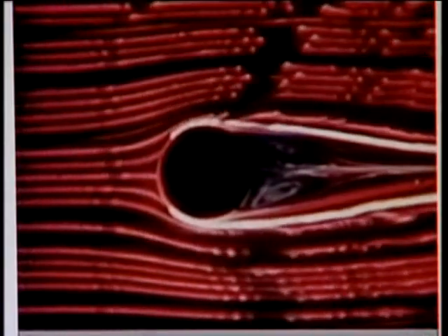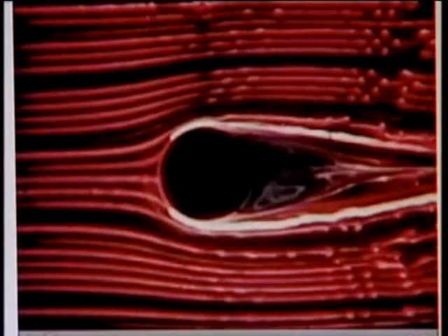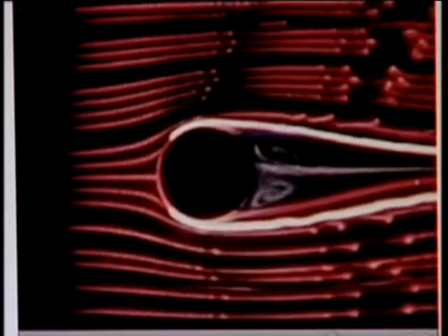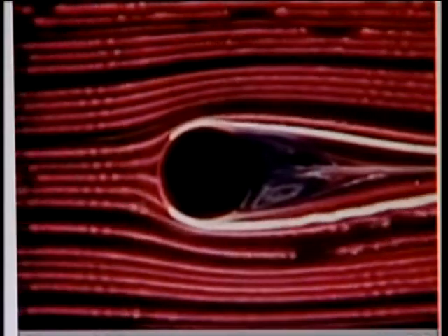In this figure, we can easily appreciate, as this fluid is approaching towards the cylinder, up to this point we have fluid which remains attached, and after this point this fluid gets detached, or this boundary layer gets detached. So this is the zone where fluid is not attached with the cylinder.